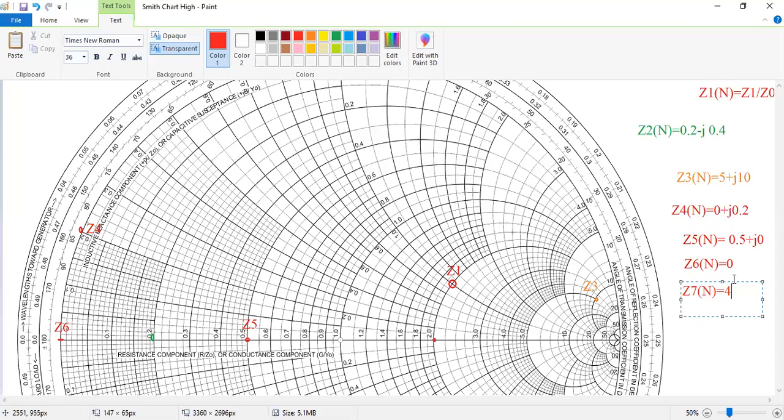So 4 is possible. In the resistance, minus 4 you cannot locate, because the reactance due to an inductor is positive and the reactance due to a capacitor is negative. So there is no negative real part. This is the resistance part, which may be 4 only, or whatever real value, 4.4, 0.1, whatever it is, but it will not be negative. Okay, 4 plus 6j. We'll take minus, since we had not taken many examples of minus. Okay, sir. 4 minus 6j.